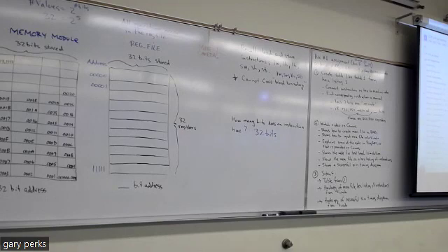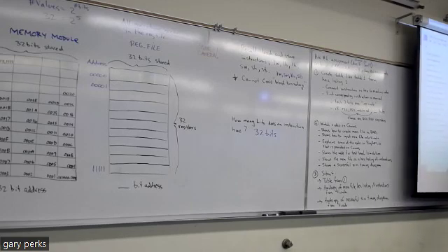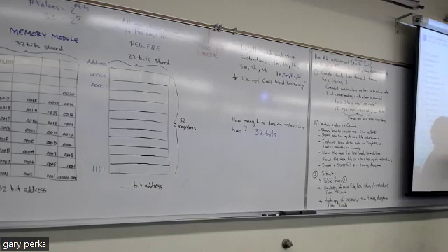But what we want you to do in this assignment is take each of those instructions in hex and convert them to binary. That's what was done in this table here. Here's address 0, and here's the binary for 00500293. Remember how you go from hex to binary directly? Groups of four, right? Here there's a 3, and there's a binary 3 grouping. Here there's a 9, and there's a 9.